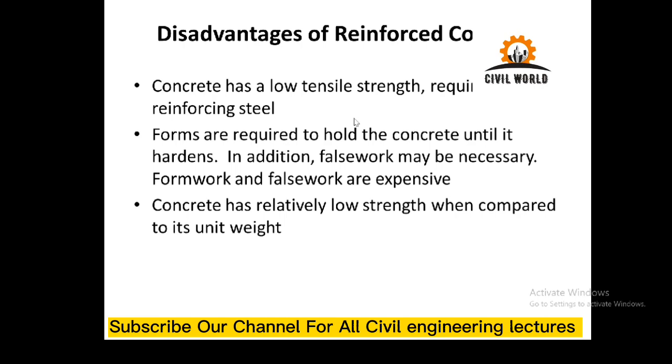Then, because the concrete is in plastic form in the initial stage, it cannot support its own weight. So temporary structures and formworks are needed to support it until it has acquired sufficient strength to support its own weight and some additional construction weights.